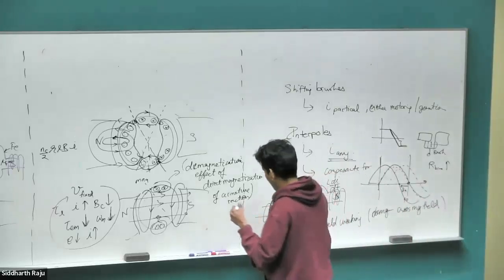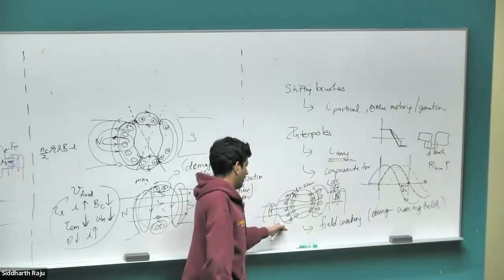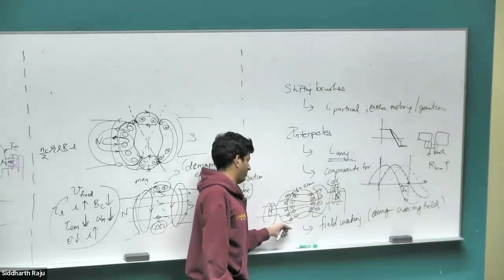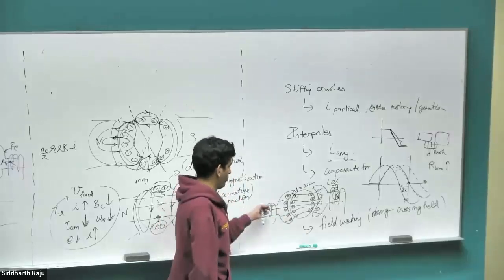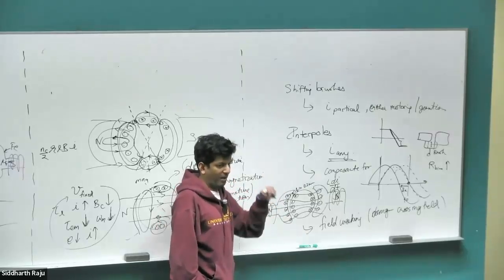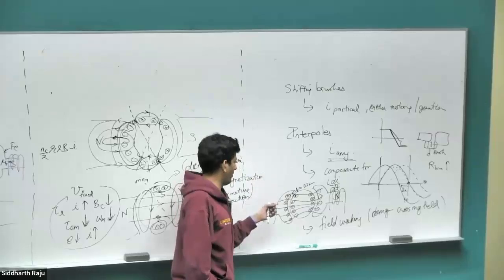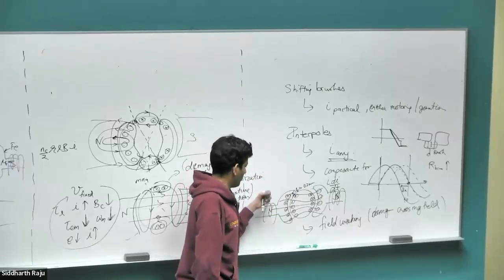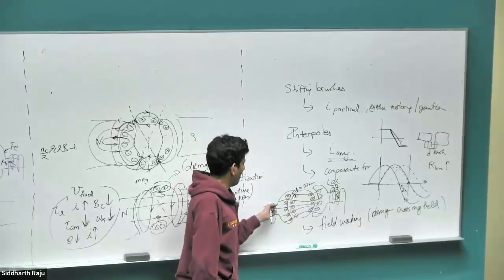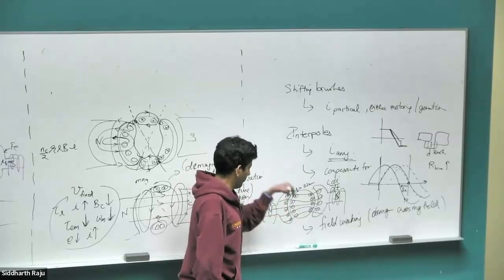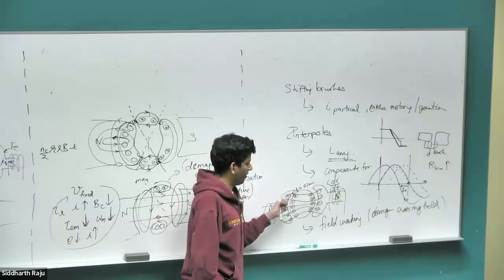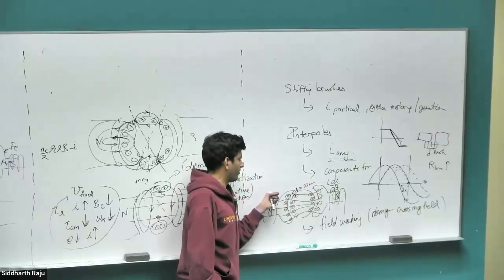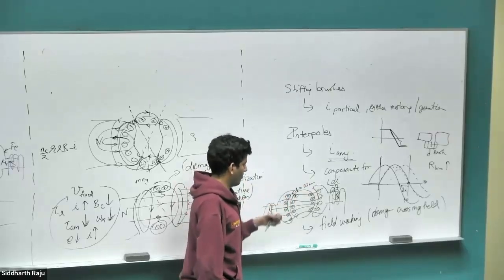Right? And especially in very large motors, this is quite an expensive structure, because in the case of low power motors, when you have magnets, of course, you can't do this. You can't drill holes in the magnet and try to put conductors in them, it won't work. So you would have a field wound motor where the magnets are electromagnets, and then you'll have slots on the stator structure itself where you can put additional conductors, which end up being quite expensive to create.